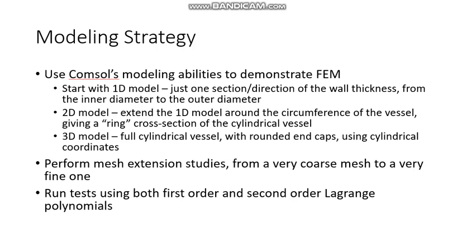My modeling strategy. For my modeling strategy, I plan on taking advantage of COMSOL and its ability to demonstrate the finite element method, and also its ability to give out solutions to the equations, paying close attention to the hoop stresses, which are the stresses along the side of the cylinder. I can start with a 1D model, which is just a section of the wall thickness, basically a line from the inner diameter to the outer diameter of the wall.